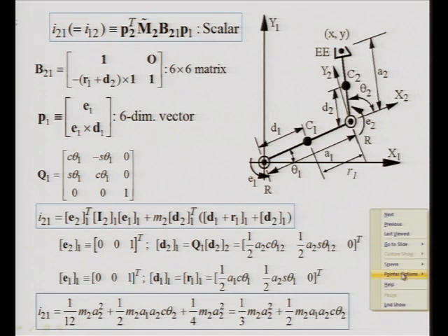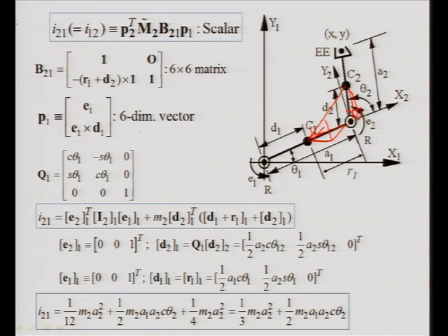So, it will be the following. B21 is this vector actually, no, it says minus R1. So, this is R1, so minus R1 is the negative side here, and D2 is this one, but minus D2 will be just opposite. So, B21, minus R1, D2, effectively means the vector denoting the mass center of the first body with respect to the mass center of the second body.